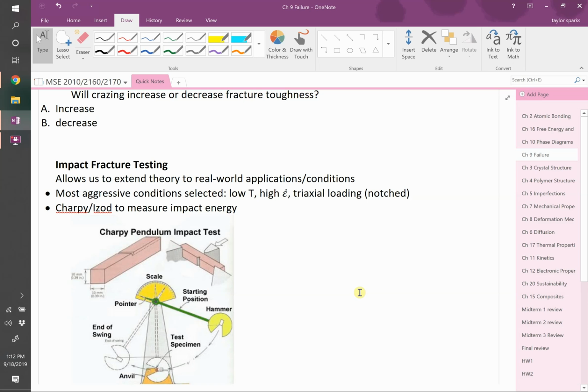Oh, yeah. When you're doing tile and you need to cut a tile around the toilet bowl, that's a pain in the butt. But if you take a scribe, you can often just snap the tile right where that scribe was. Why is that? Normally, if you take a pair of pliers and twist on a tile, it's going to shatter everywhere. But if you pre-crack it, then think about what you're doing.